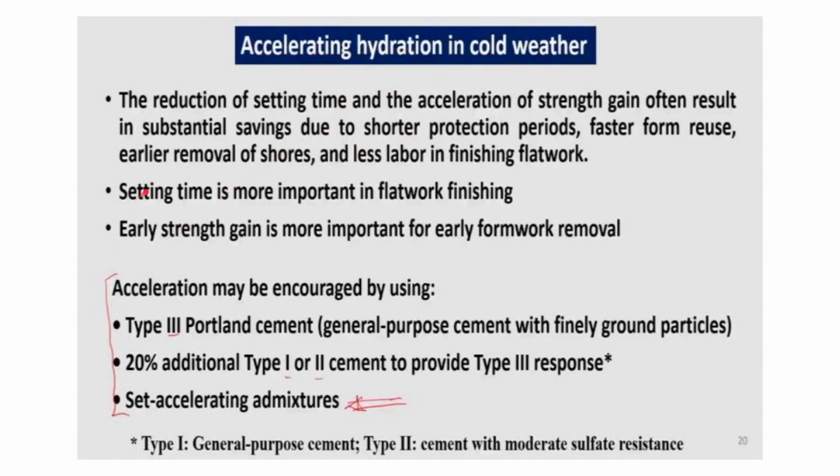Setting time is more important in flat work finishing, because the concrete needs to stiffen quickly so that we can work upon it and do further construction. Early strength gain is more important for early formwork removal.